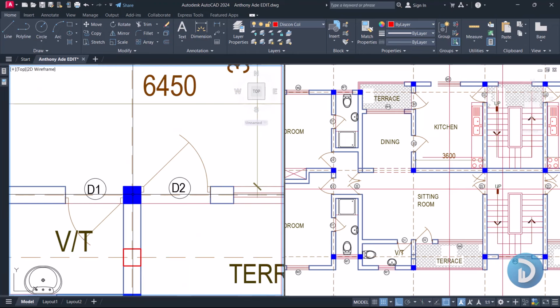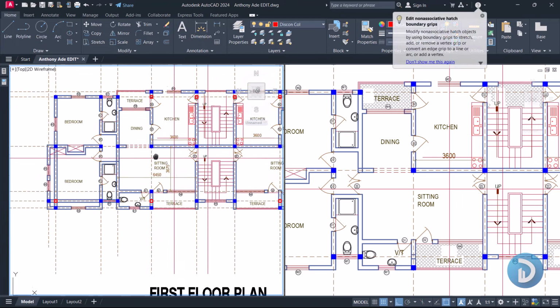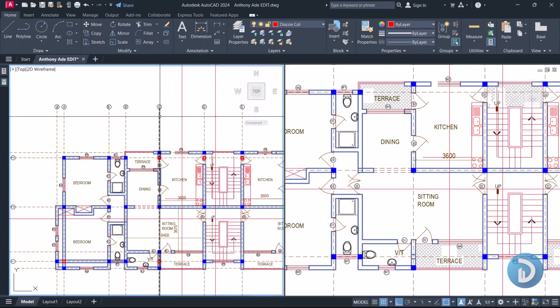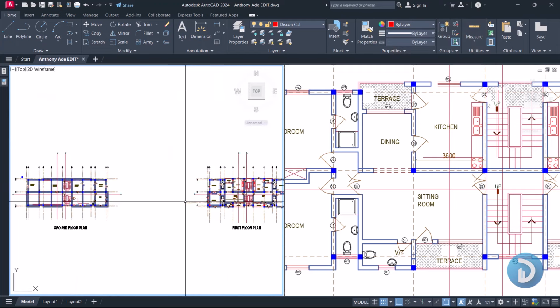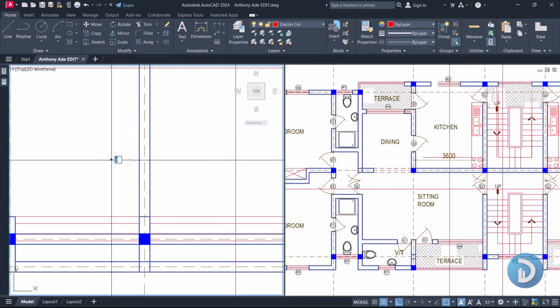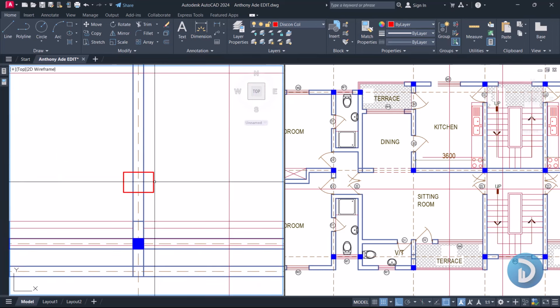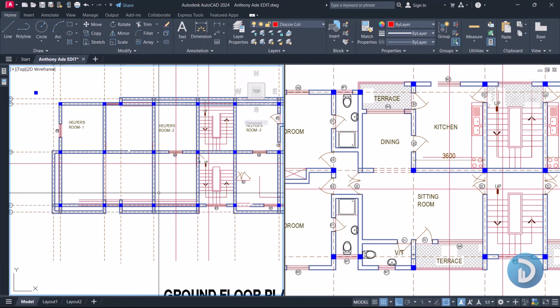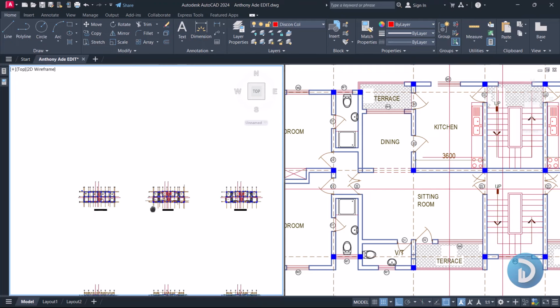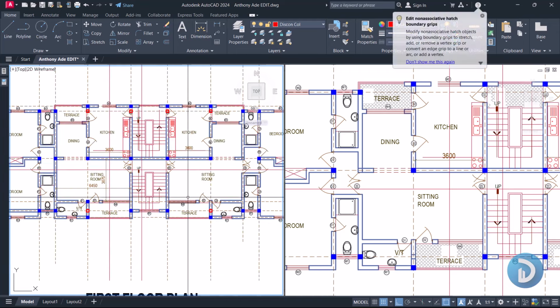And you don't have to worry about this very column coming directly on the slab below it, because we previously have a beam running directly on grid line C at the ground floor. So the column will just have to rest somewhere around this part. Okay, so the column will be introduced somewhere around this part, which is actually on a beam rather, and not directly on the slab. Okay, so the modification we've made on the left hand side, which is here, we'll also get to make it on the right hand side.